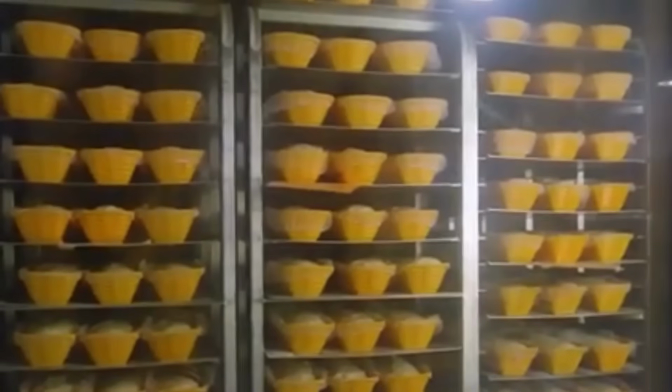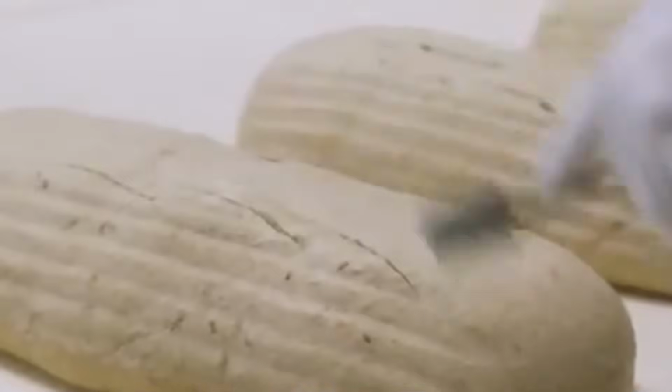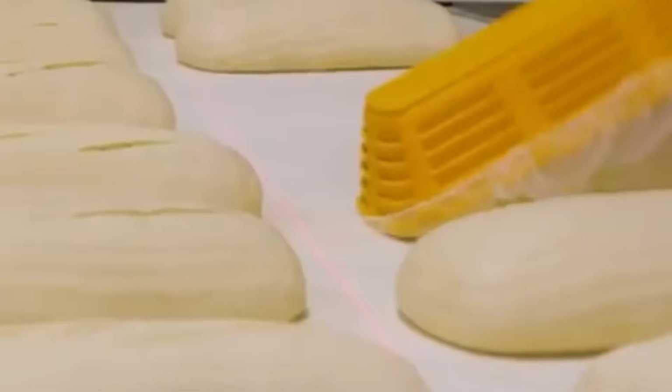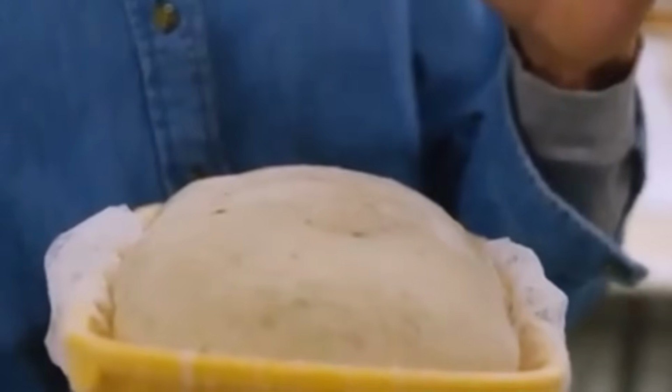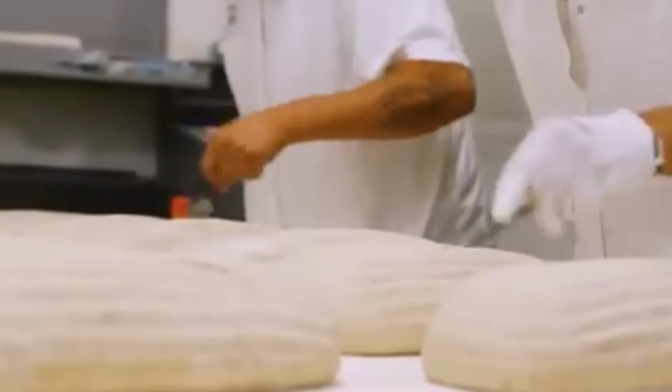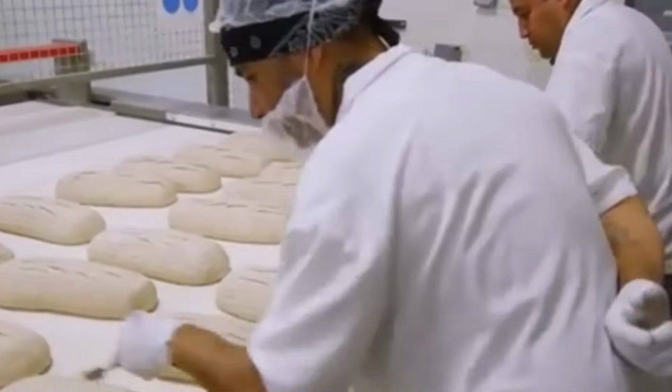Once divided, the pieces are dropped into intermediate proofers, tall, climate-controlled chambers where the dough rests in a carefully maintained environment of warmth and humidity. It's here that the dough begins to ferment actively for the first time. The yeast, having been activated during mixing, releases carbon dioxide, expanding the structure from within. But this step isn't about final rise. It's about conditioning the dough, allowing it to relax after the physical stress of division so it can be molded without tearing. After a set number of minutes, each portion travels via conveyor to the molder.